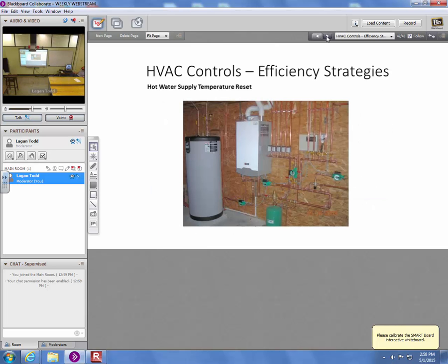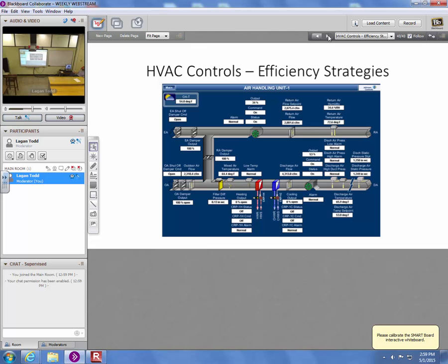So what, then, do I have a couple more slides? That's the same slide we saw last week, for a typical boiler system for residential, radiant or whatever. This one I just threw in there because I had it and I didn't know if I was going to use it, but this gives you an idea of a more complicated air handler, and this isn't even the most complicated air handler, but in a commercial setting, and how many points, each of these little white boxes is telling you something. It's either being measured or a command value in the controls of that system. This is a screenshot from that interface.